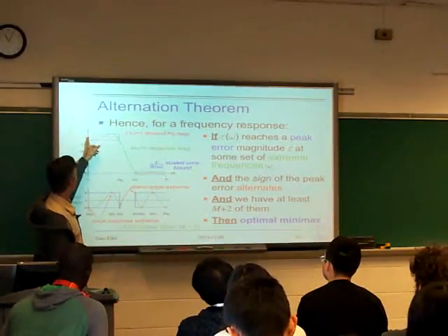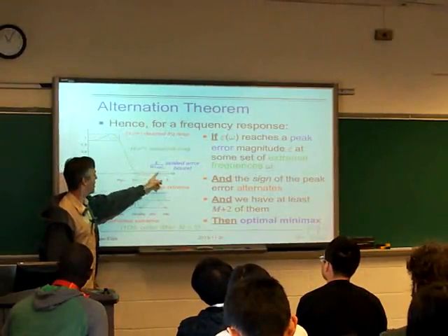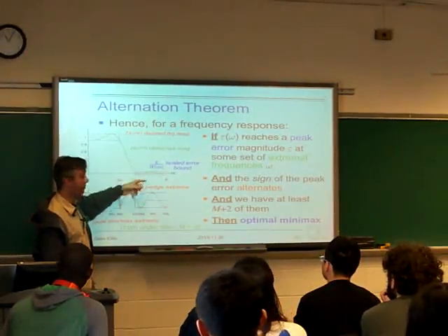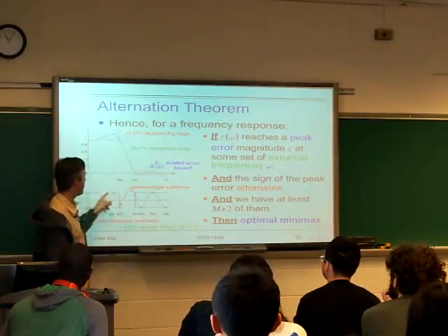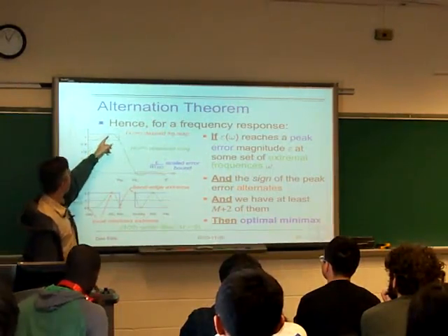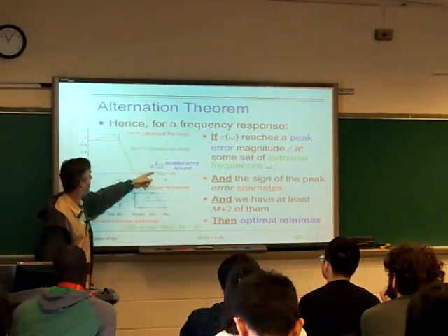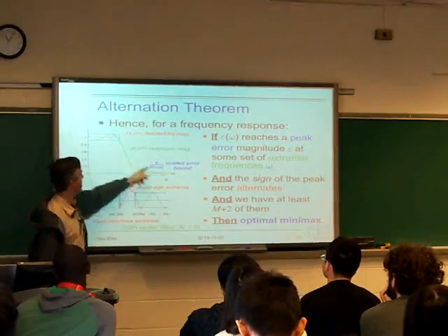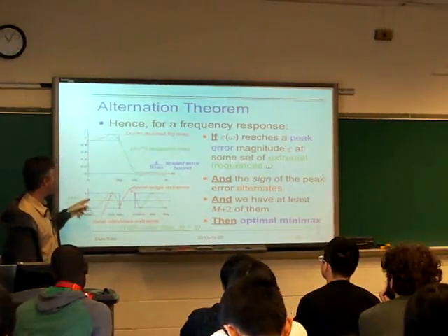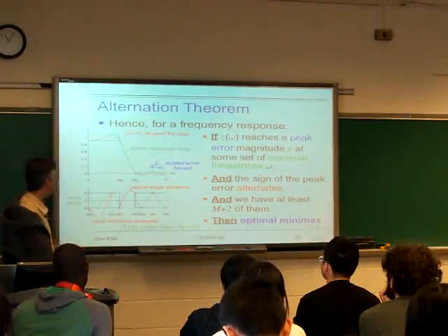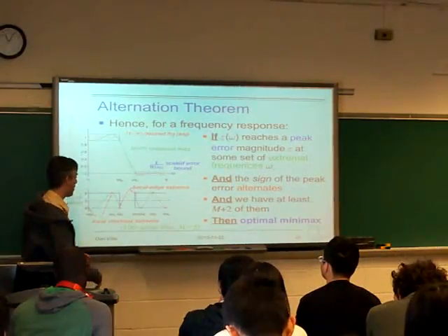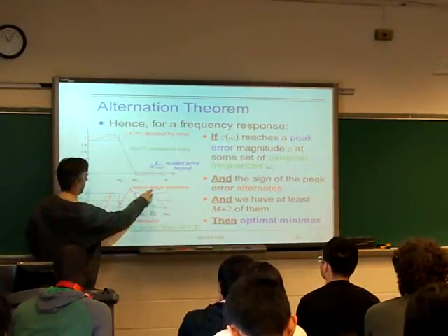magnitude response in green, the desired response in red, with the bounds, the scaled bounds in blue. And so here's the weighted error function. And here are our ripples, our local ripples, right, that came from that polynomial. And we see that apart from the ones at the ends, we've got 1, 2, 3 of them. So when we do this error function, we find that there are now, here we've circled in red each of our extremal errors. And so we get them from these ripples.